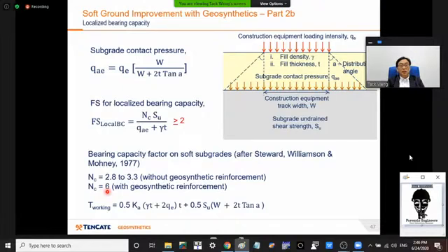In the same case as the pile embankment design, you want the reinforcement to be able to pick up the outward push of this load, as well as to try and bring in an inward shear stress from the underside. So this will allow you to work out the tensile strength required.